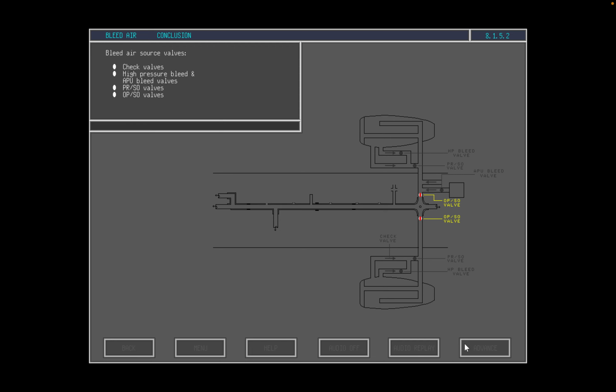The OPSO valves remain open in the event of overheating in either system to allow engine anti-icing from the other source. The starter valves open to allow APU or ground supply bleed into the engine starters. Starting is also possible using cross-bleed from the other engine. The shut-off and regulating valves open to allow bleed air into the engine nacelles for anti-icing. The shut-off and modulating valves open and close to allow bleed air into the wing and tail leading-edge compartments.